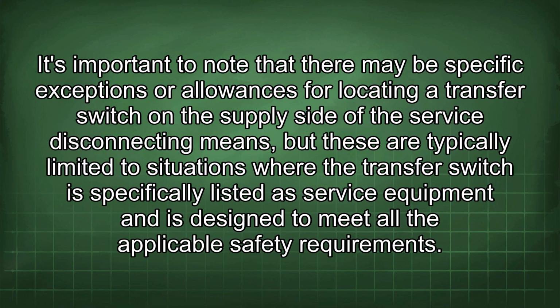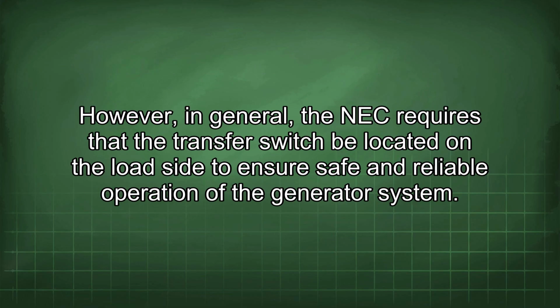It's important to note that there may be specific exceptions or allowances for locating a transfer switch on the supply side of the service disconnecting means, but these are typically limited to situations where the transfer switch is specifically listed as service equipment and is designed to meet all the applicable safety requirements. However, in general, the NEC requires that the transfer switch be located on the load side to ensure safe and reliable operation of the generator system.